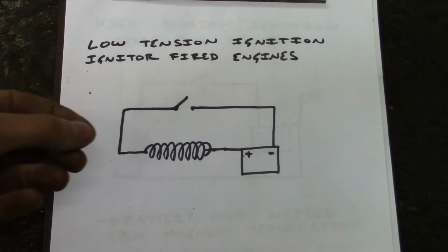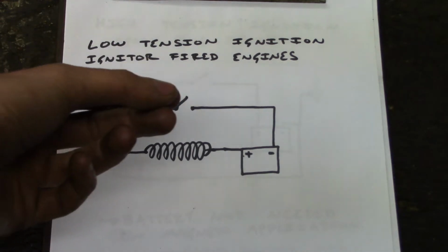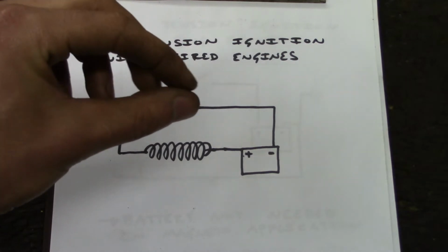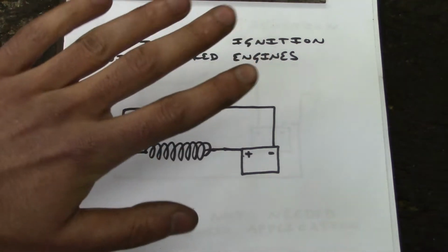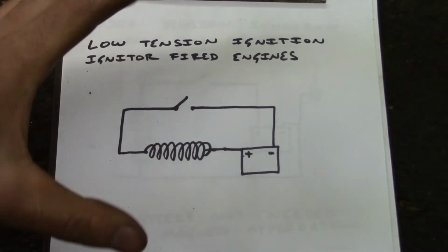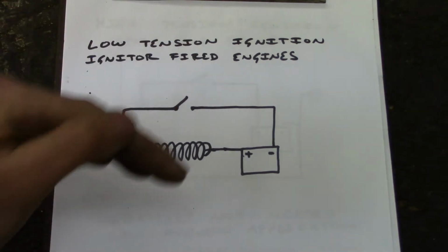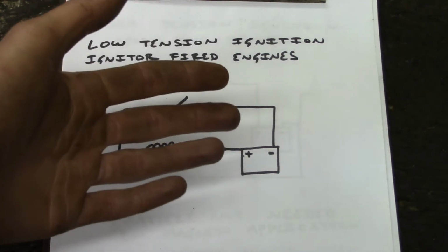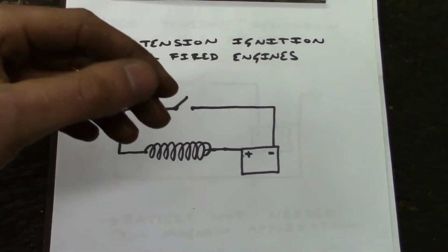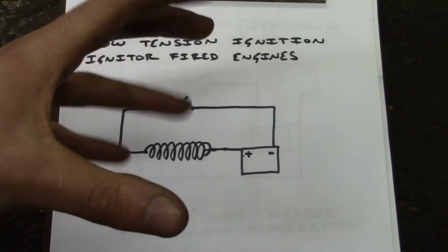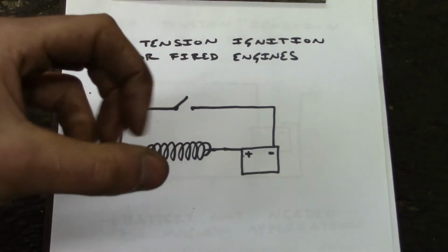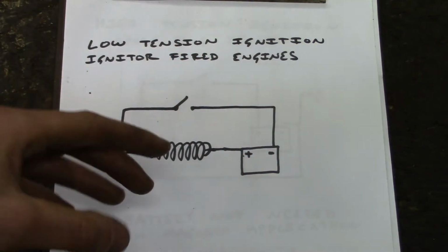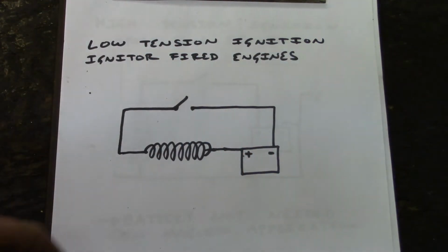And that's important because you need high voltage to jump a spark gap inside an engine, inside a cylinder. I'm getting a little off track here, but when the piston comes up on compression, you have high pressure inside the cylinder, and that means all the air molecules are tighter together, so it takes more voltage for a spark to jump through that compressed air inside the cylinder.